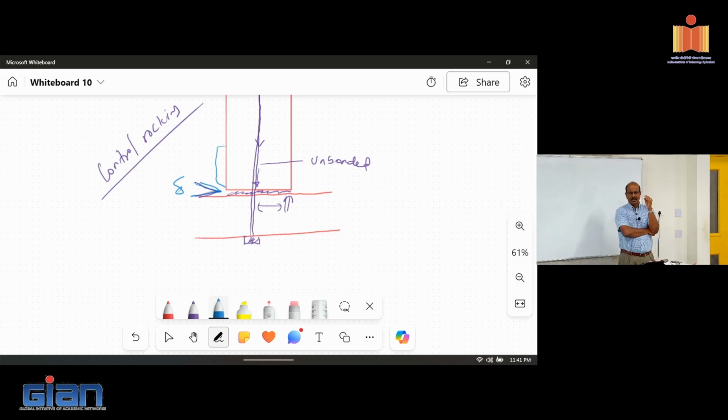So all you have done is push all of the cracks to the interface. It's not something you can do with cast in place, and we are not trying to match the two together. We are developing equivalent resistance in the two systems. I'm letting precast behave like precast. I mentioned that, like with UHPC also, some people are going to go back and force them to behave like cast in place. No, it's UHPC. So you have to figure out what the UHPC is going to do.